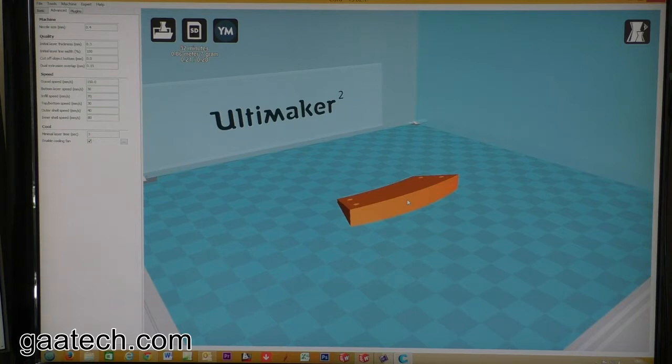In my printer, I set the type of material that I'm printing, and I set the temperature of the heated bed and the temperature of the extruder. I believe on some software those settings get set in this space, so when you're creating the model you choose the material and that information gets stored on the SD card, so when the code is put into the machine it already knows the settings, whereas on my machine, the Ultimaker 2, I can change the settings on the machine itself.